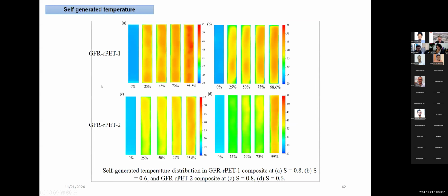But here we find that the temperature data now supplements the observation. So the observation is that the fatigue performance is better. Why is it better? One thing I can say is that when I compare the top figure, which is for without modification, RPT1, at the same stress levels of say 0.8, the temperature rise in the modified one is very less in both the cases. So this is one reason. Again, an observation telling me that the damage accumulation is less, and that is why the fatigue performance of the modified system has improved over the unmodified system.